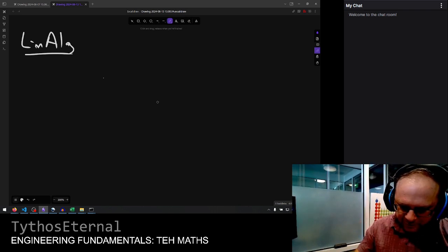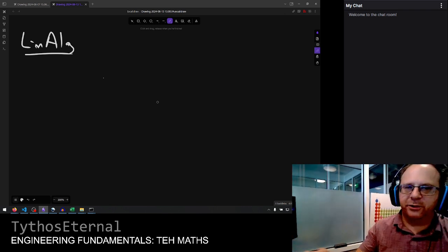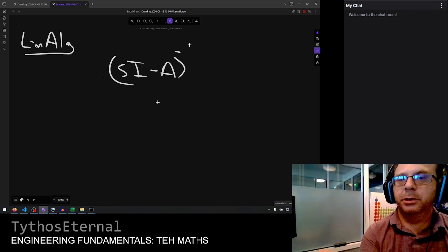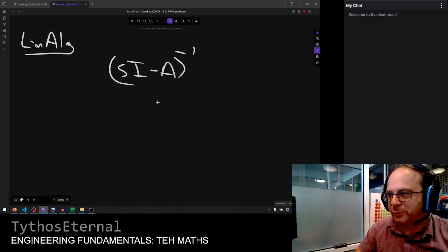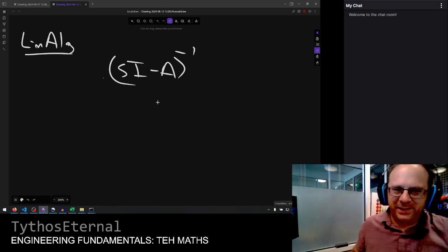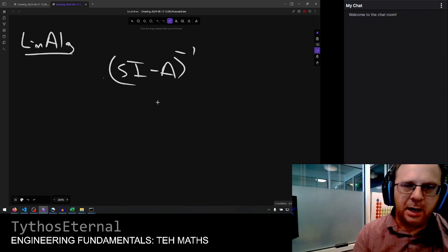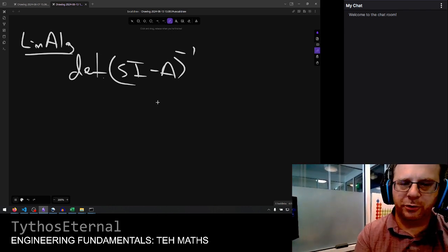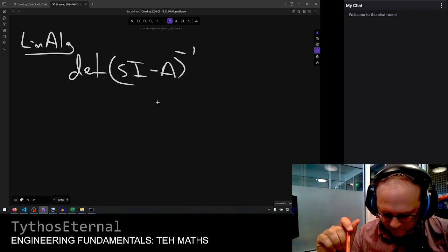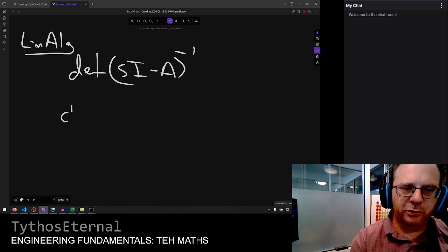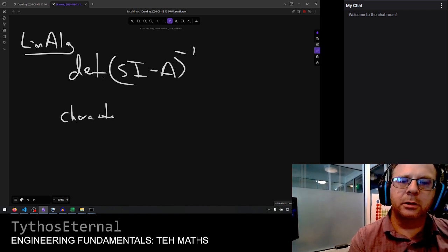Okay, so there are algebraic properties of that system in particular, like is this invertible, right? If that's not invertible, that tells you interesting things about how valid your assumptions of this system and the linearity of its dynamics are. So I mentioned the determinant of this matrix. It will tell you interesting things as well about the stability of the system. You can back out the characteristic equation from that determinant.